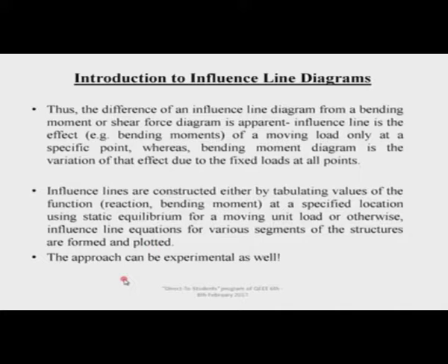Both are equally useful. Most of the time we will be tabulating the values at critical locations and joining them with lines, which are suitable for statically determinate structures. We will see that they are straight lines, and we will explain why. For statically indeterminate structures they are curved. So, an equation may be better, but sometimes it will be cumbersome. So, we will go for determining the values at discrete locations.